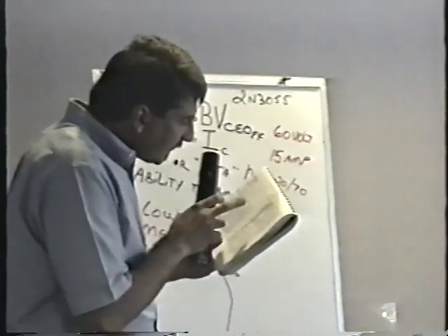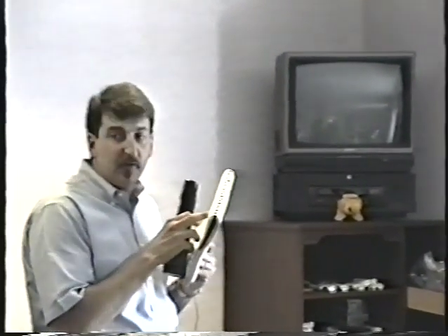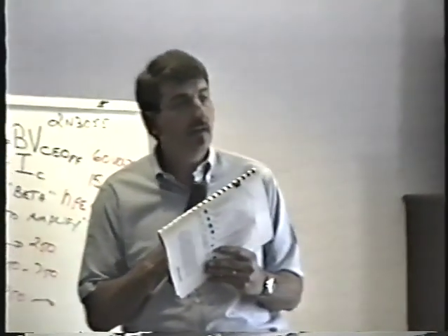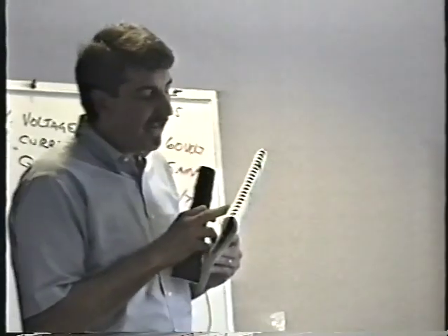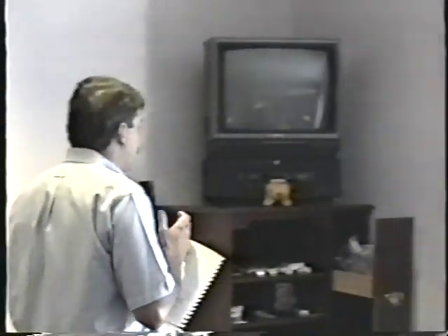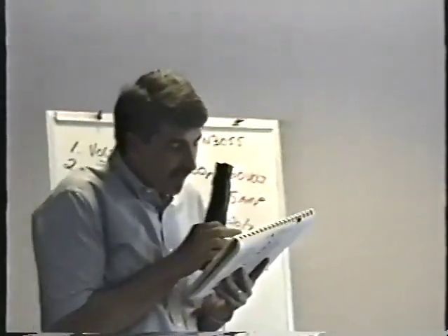Anyway. All right, let's look at a few more. How about under 15 amps, 80 volts, 2N5880? Could I use that one? Why not? Yeah, you can. Why not? Could I? 5880? Yeah. It's PNP. What does that mean, Hondo? I can't use it, right? Reverse polarity. Right, the polarity would be reversed. Okay, so I can't use that one, but we can get pretty nuts here.